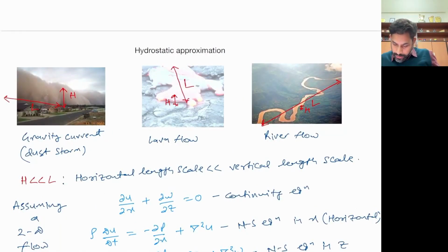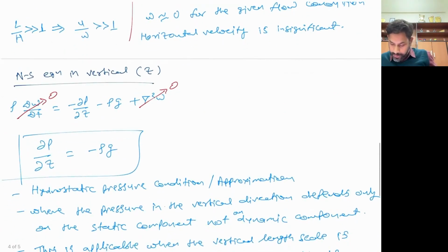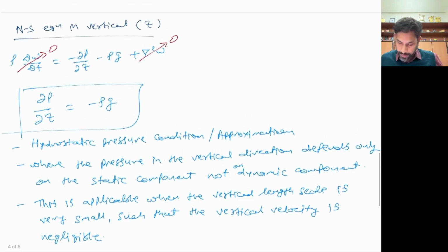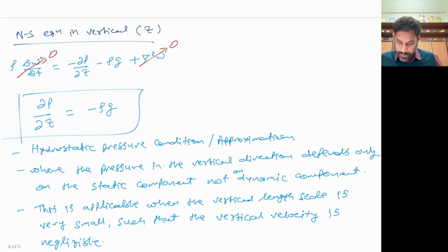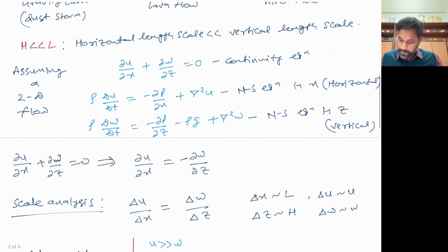here, such that we get rid of the vertical velocity and we make our problem much simpler than how it was originally there. Right, and now if we have simplified the vertical Navier-Stokes equation, we can also simplify the horizontal Navier-Stokes equation, and that I will leave for you because you have to expand capital Du by Dt and also del square u.